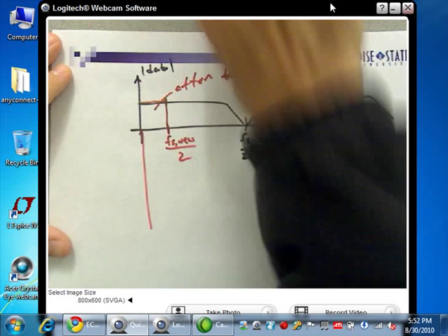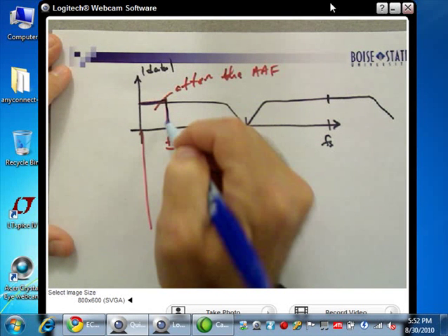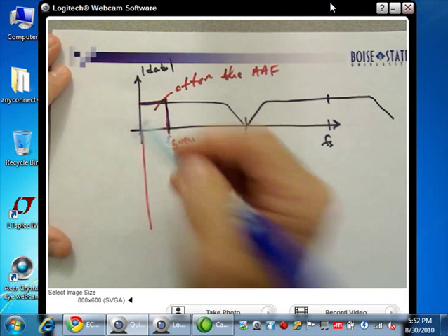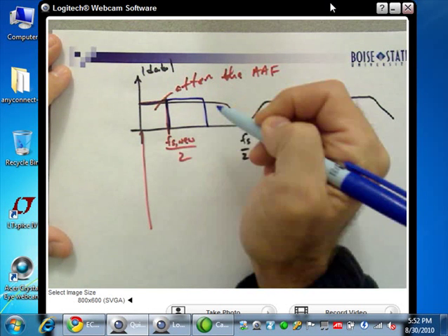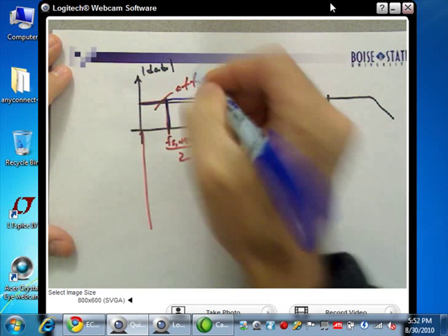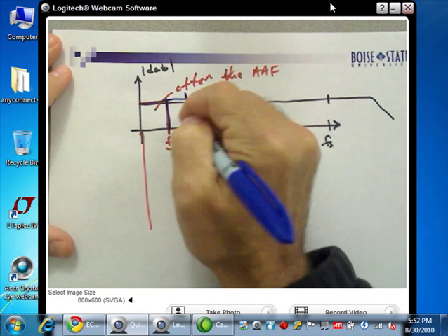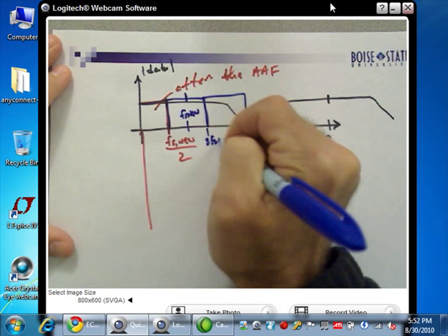And then as I resample at the slower rate, and let's just draw it here because they're really anxious to get in this room. So I redraw it at the slower rate, I get my aliases because I'm resampling at the lower rate. So I get this. So this would be my f sub s new. This would be 3 f sub s new over 2.